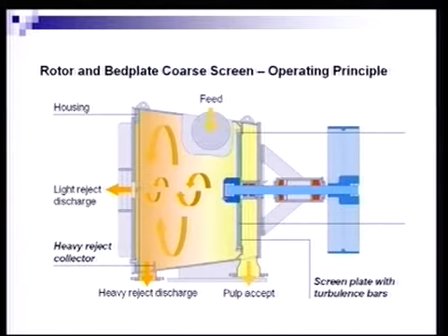remove that styrofoam contamination. Then the end of the pressure vessel here is flared out in order to promote this circulation that happens inside the rotor, inside the secondary screen here, and it has a heavy outlet discharge. It keeps the heavy material away from the rotor and gives you better, of course, longer rotor life, and provides another method for sand removal, staple removal, and heavy debris removal in the secondary coarse screen.